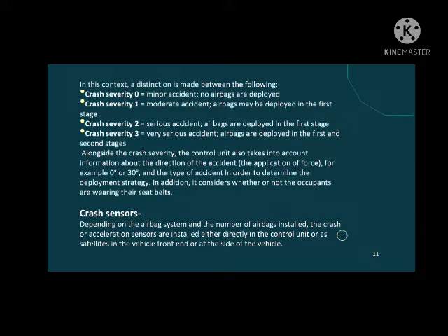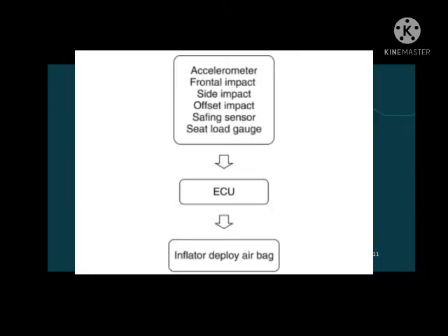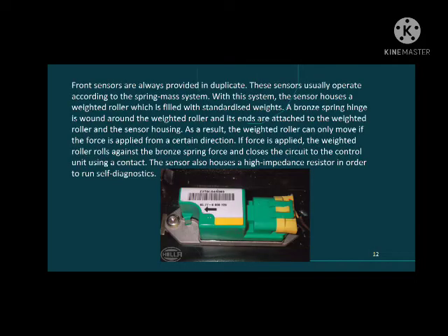When the vehicle decelerates due to a collision, the sensor detects the deceleration. This sensor is an electronic accelerometer. The ECU decides whether to inflate an airbag or not based on the waveform obtained from the time of collision. The sensor may detect vehicle acceleration whose impact is comparable to a collision, such as when the vehicle collides against a curb, and the waveforms are obtained from the frontal collision sensor. When the ECU decides that an airbag should be inflated, ignition current is applied to the inflator.